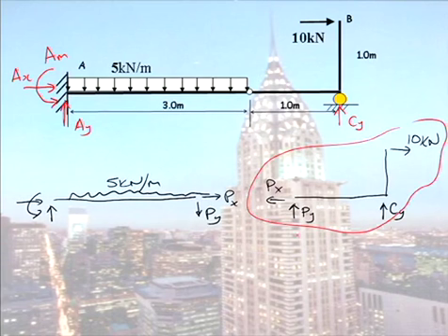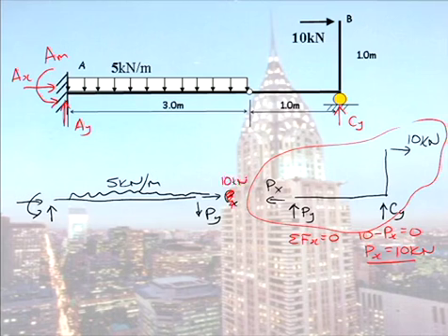So looking at the right-hand side, all the forces in the x direction equal 0. So 10 minus PX equals 0. So we know the horizontal force passing through the pin is 10 kilonewton. So I'm now just going to scribble that out and call that 10 kilonewton. And then I'm also just going to draw this horizontal reaction in the direction it occurs, 10. So now we have horizontal equilibrium.